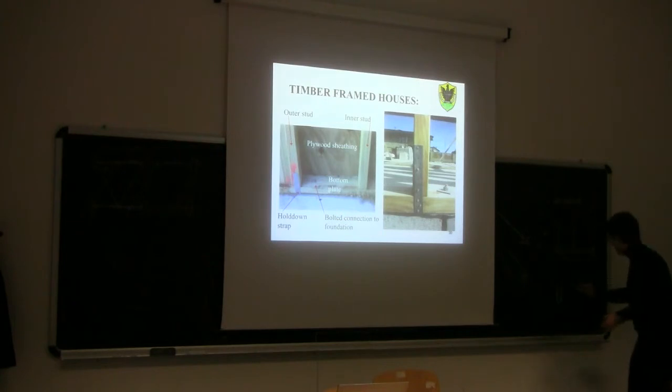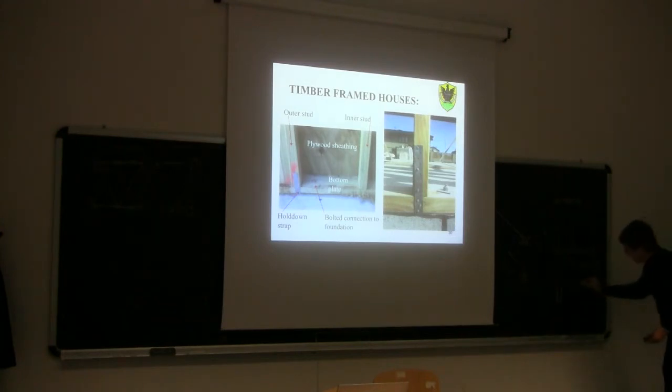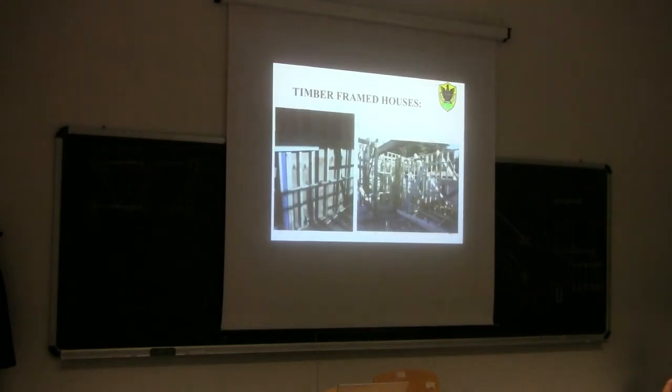So you have a bell frame like this, let's say. And this is this connection here. They're just made to take together these elements. So the bell frame is prefabricated outside, then it is delivered on the building side. It is placed, you see, vertically with some temporary bracing. You see this diagonal here. Those diagonals are temporary bracing.